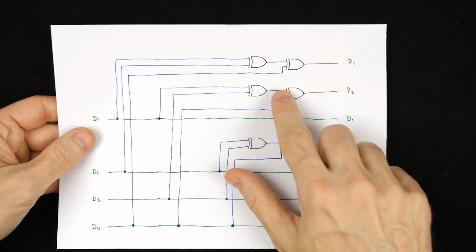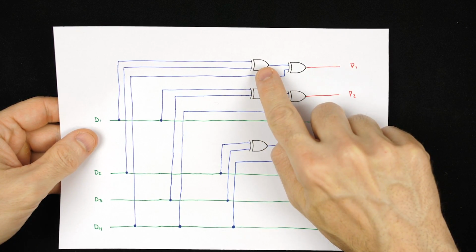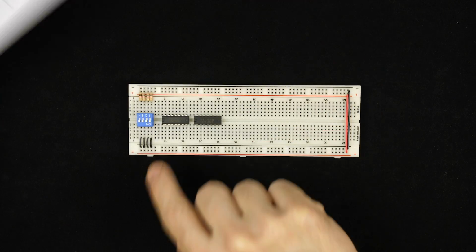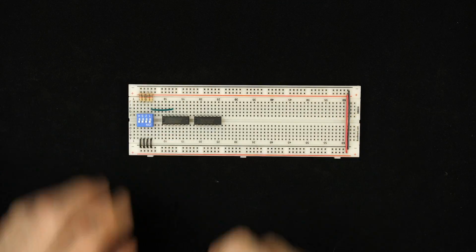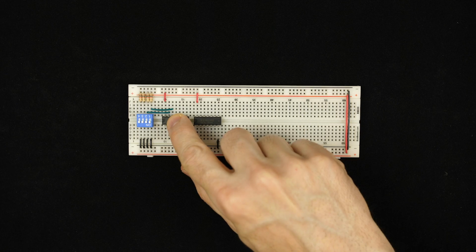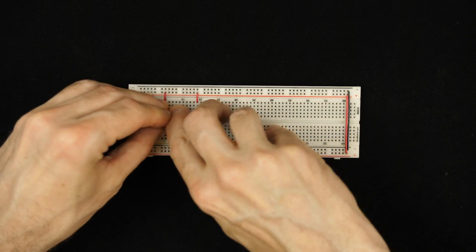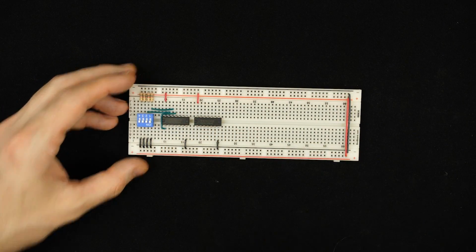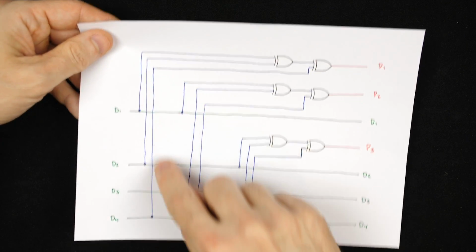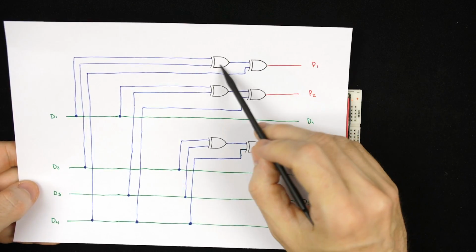Now I just need to wire this up just like this. So I'll take the first XOR gate, which will be this one, and tie it to D1 and D2, which will just be switch 1 and switch 2 here. And actually, before I forget, let me hook up the power and ground to each of these chips as well, so they're powered. So those are two inputs of an XOR gate, and then the output of that will go into the input of another XOR gate. There's the output going around to another input, and then the second input of that goes to D4. And so that's these first 2 XOR gates hooked up.